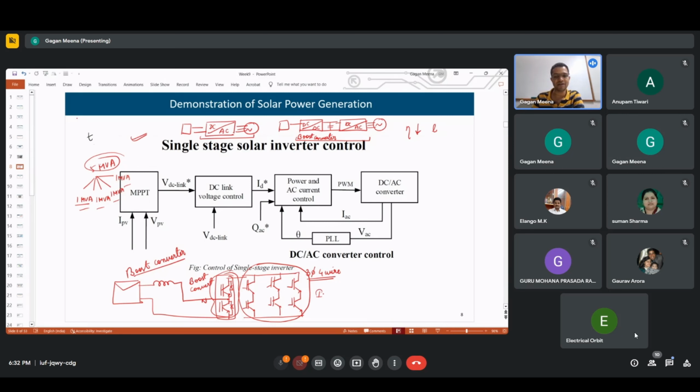Suppose I have a distribution system and I want to integrate storage, just as we saw in one case study for optimal storage siting, right? The IITR distribution grid was modeled inside the RTDS. So inside RTDS, I have the model of the IITR distribution system. It is not the actual distribution system, but it is a model which will behave like the actual distribution system. So now, what I want to know is the optimal nodes or buses where the storage should be connected.